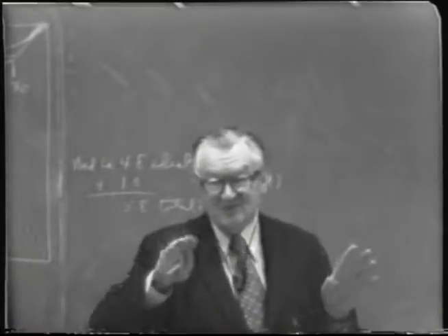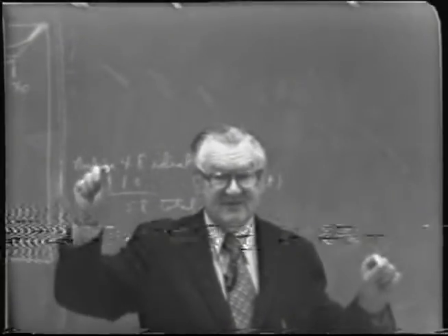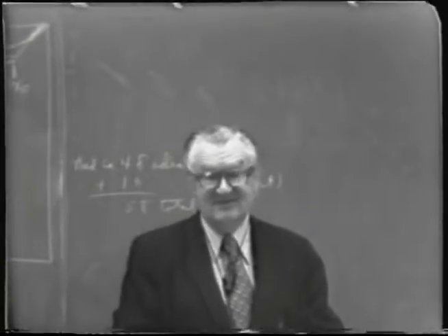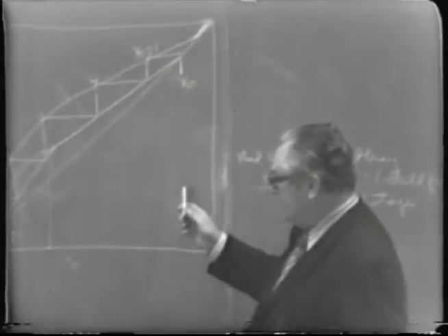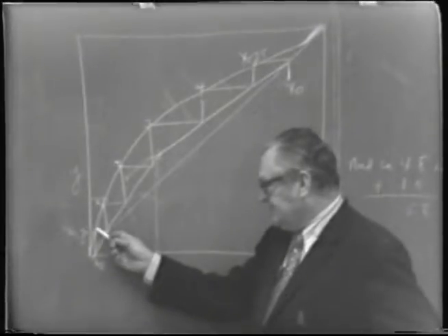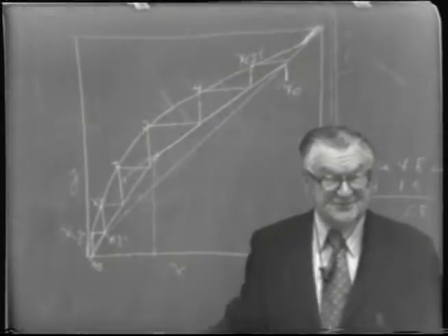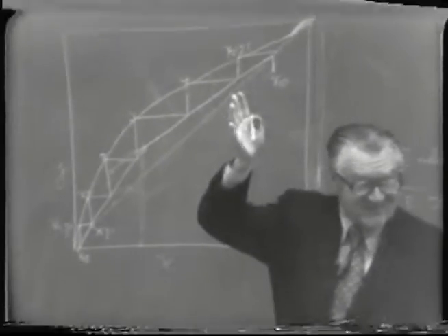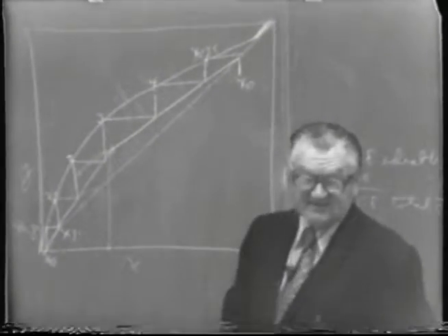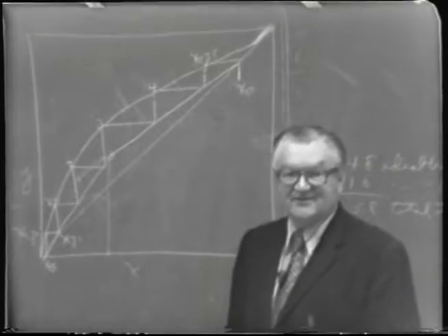To be rigorous about it, you'd have two fractional stages at either end that add up. Most likely it'd come out that way, or in other words, the step wouldn't coincide exactly with the specified bottoms composition or the distillate composition. It'd be a fraction of a tray, but it should be exactly the same number of steps if you draw it accurately.